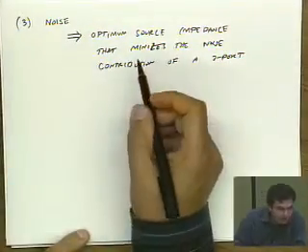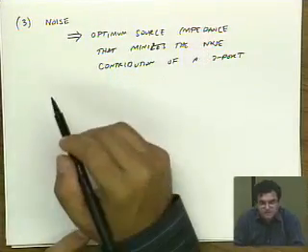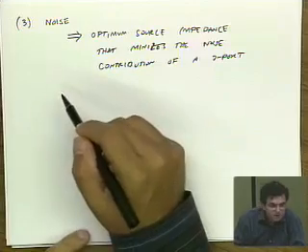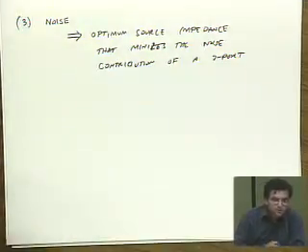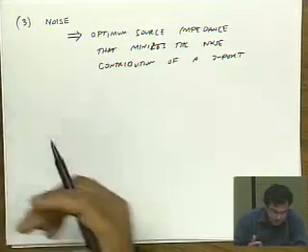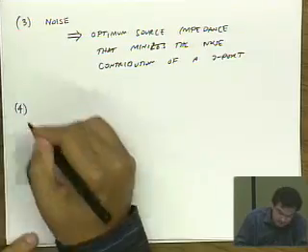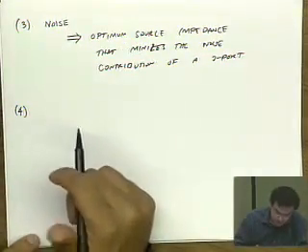And in fact, this optimum impedance is not necessarily the same as the optimal impedance for maximum power gain. So in some cases you have to make a compromise and ask yourself, do I want to match for gain or do I want to match for noise? That's another reason that we would impedance match, and we'll go into this in a lot of detail later in the course.